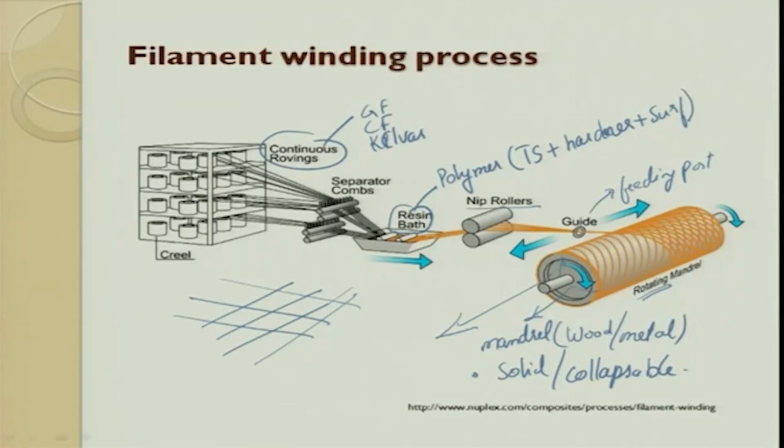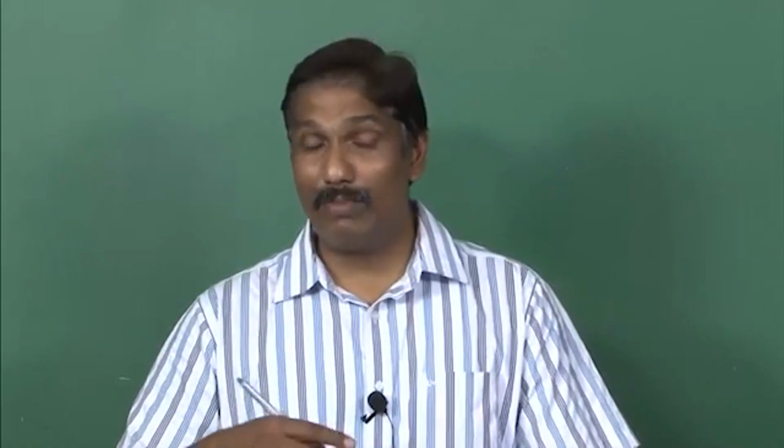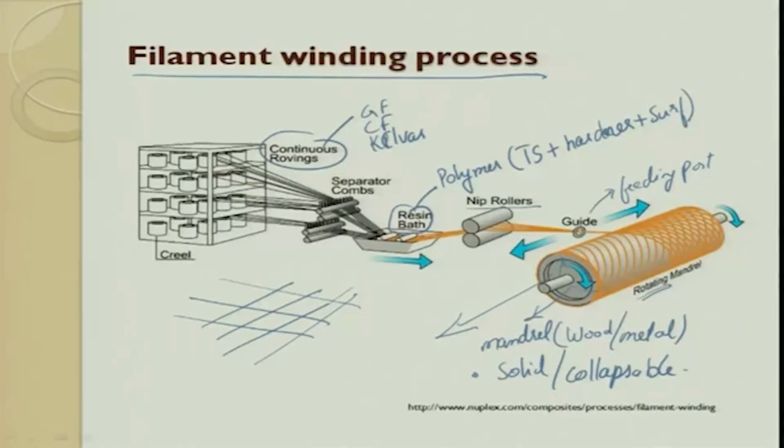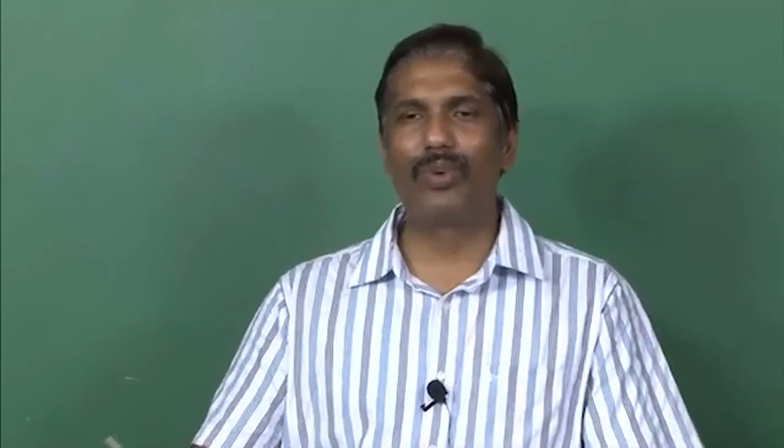Two ways are used: either exclusively composites, or they have taken cement concrete and made a column, and the column is protected by the filament winding process using glass fiber to avoid corrosion and to enhance the strength property. The other thing is that today they talk about self healing, or how we make sure that defects which happen on the concrete are prevented from growing further.